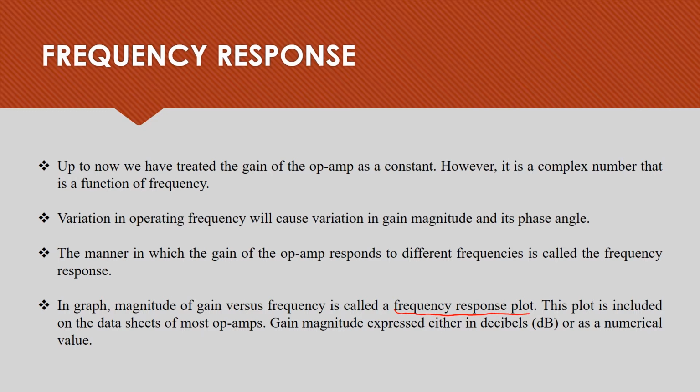This plot is included on the data sheets of most OpAmps. Although gain magnitude may be expressed either in decibels or as a numerical value, the frequency is always plotted on the logarithmic scale.